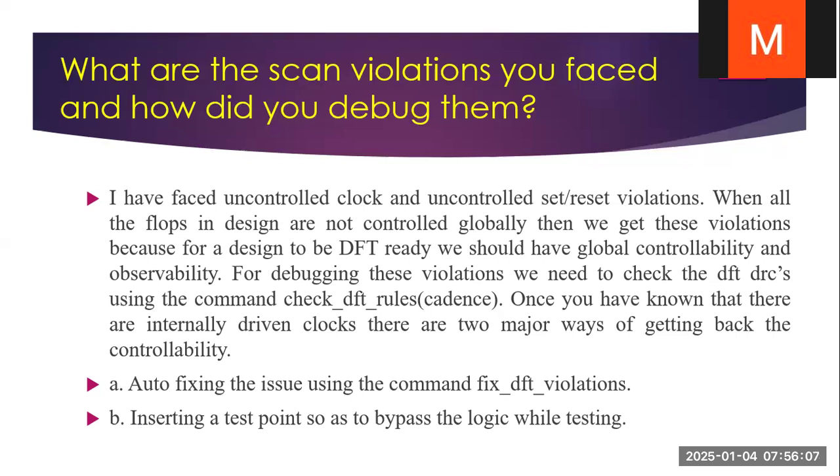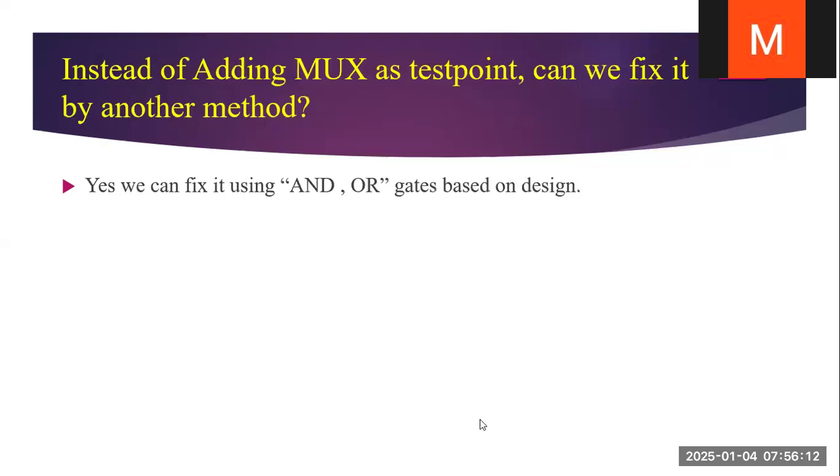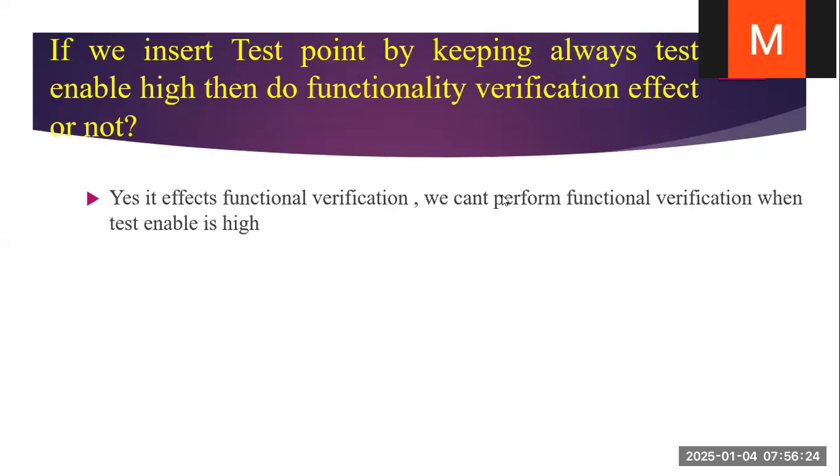Insert a test point so as to bypass the logic while testing. Instead of adding a mux as a test point, can we fix it by any other method? Yes, we can fix it. We can fix it by using the AND and OR gate based on the design.